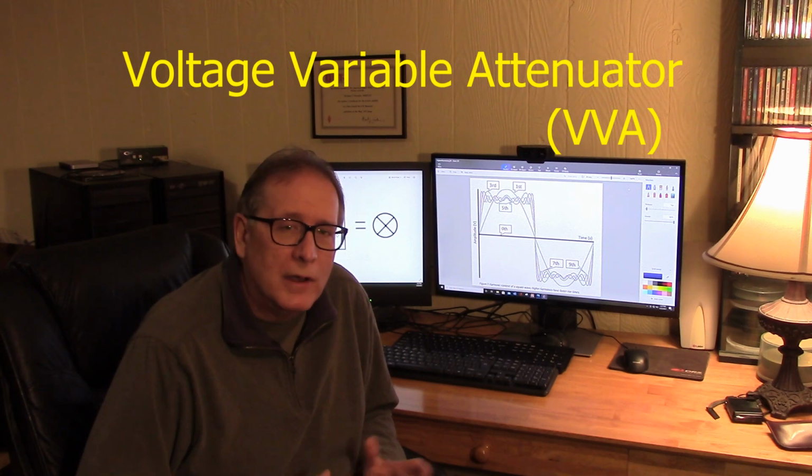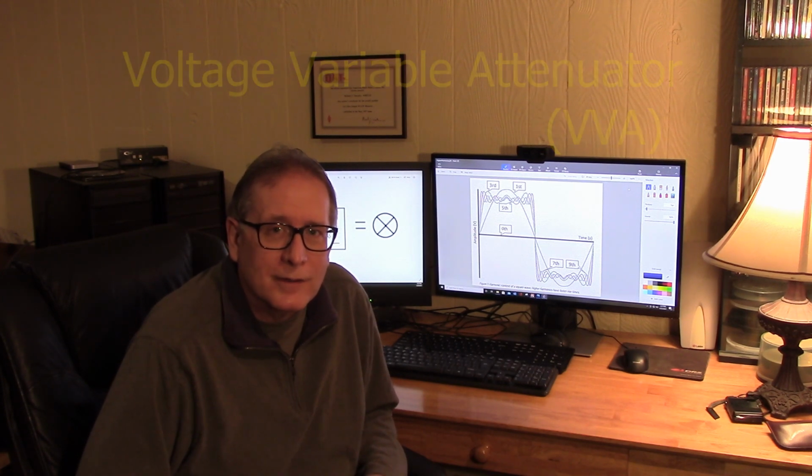Finally, we talked about attenuation and introducing attenuation in order to preserve dynamic range with an extremely limited dynamic range unit. We have an 8-bit A to D in our little dongles, and we need to preserve as much dynamic range as possible by limiting the signal going in. So I would like to try some type of attenuator that we can put a knob on and we can turn the gain up and down with the twist of a knob. So we'll try a variable attenuator circuit.